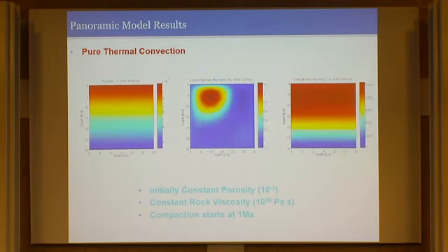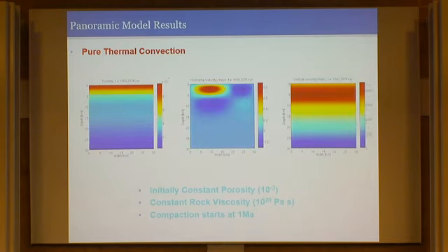As you can see, most of the downward flow is eliminated, but horizontal flow gets inherited, although it is displaced upward, because compaction in this uniform system generally does not generate a horizontal pressure gradient. So the pressure gradient driving horizontal flow due to thermal buoyancy still exists.